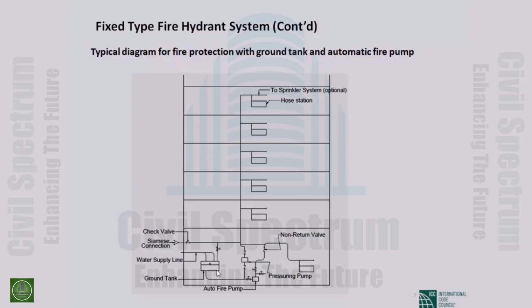During the fire, when you are extinguishing this, if there is a shortage, when the fire department comes they can also fill it by a local connection. We call it a Siamese connection. By using the Siamese connection, the fire department can directly put water into the hose system, or they can put it in the reservoir if needed by using different arrangements of valves.